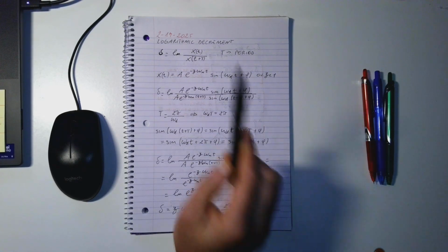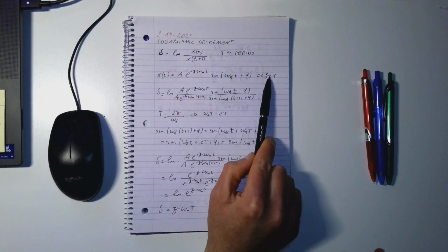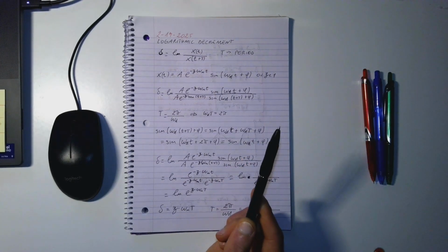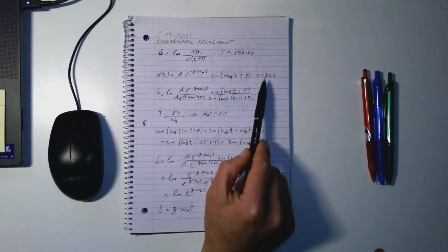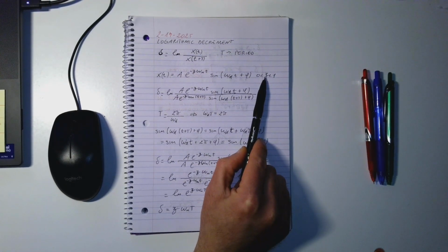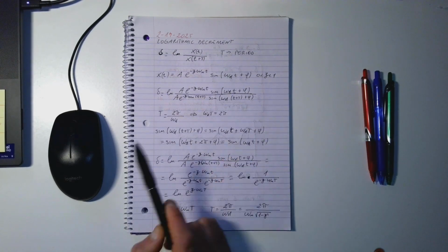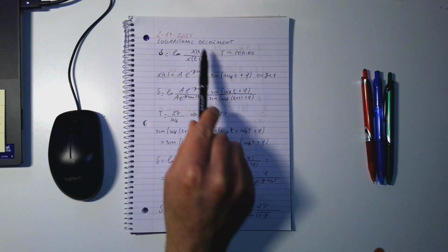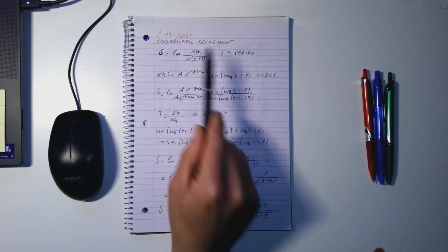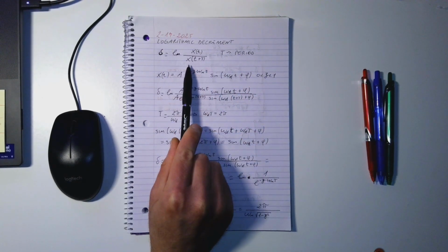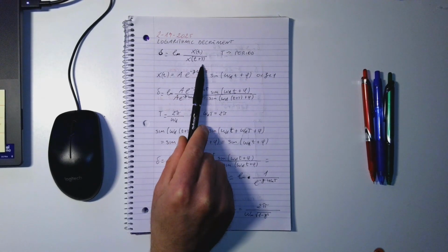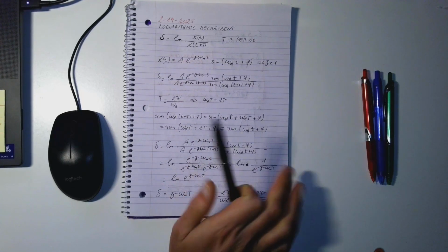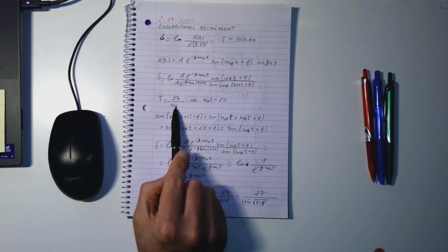How do we do that? We look at the solution. This is the solution that is valid when we have an underdamped system. Remember, zeta, the damping ratio, must be between 0 and 1. So this is the solution. When we have this solution, we can simply plug here x of t in the numerator and x of lowercase t plus uppercase T. Then we know the definition of the period, 2 pi over omega d.